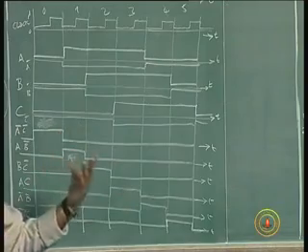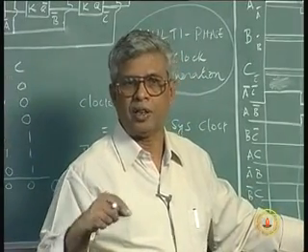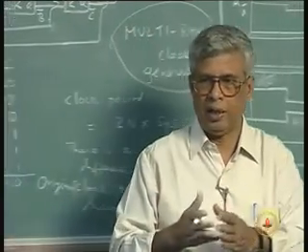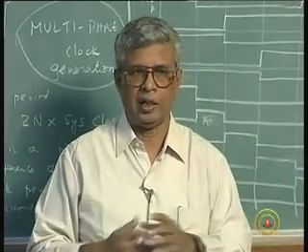So all these applications are possible by Johnson's counter or twisted ring counter, which is a basic modification of the shift register, as I said. Because shift register basically is the output of one stage fed into the second stage and shifted to the left or the right, depending on the design.